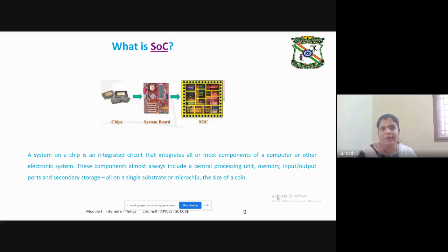Do you think your IoT devices are constrained by any factor? Say by size, memory, power, right? Do you agree with this? Your IoT devices are resource constrained because they operate on battery. Most of the times they operate on battery. If you place it in a remote area, it operates on battery. Then again, it is a memory constraint. Your IoT devices on their own don't have much memory. Onboard, you have only limited memory to read your data and transmit that data, right? You have to consider all these constraints.